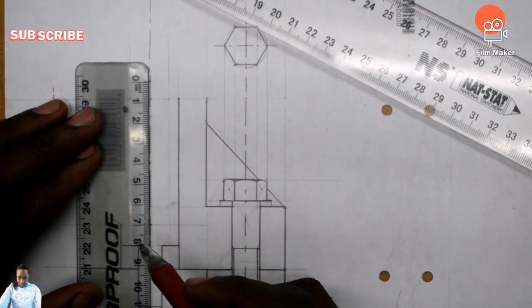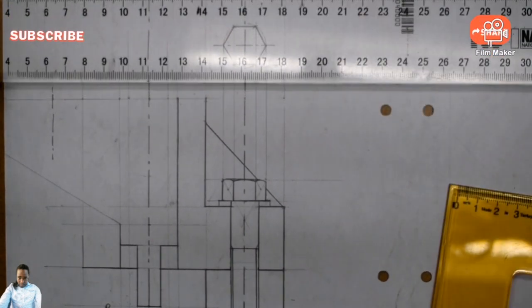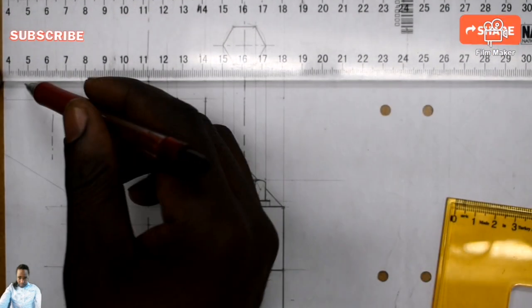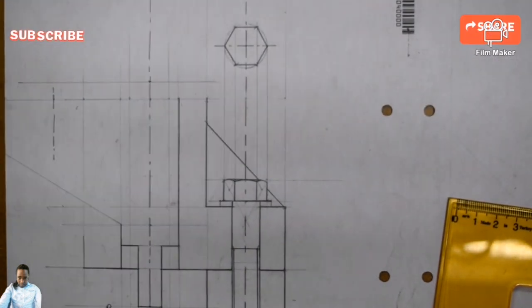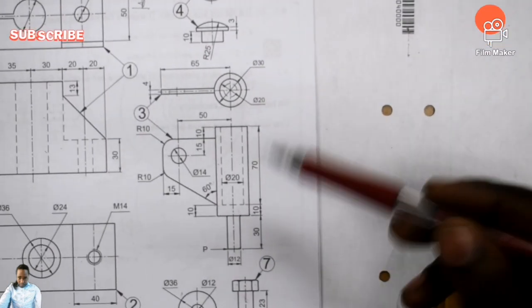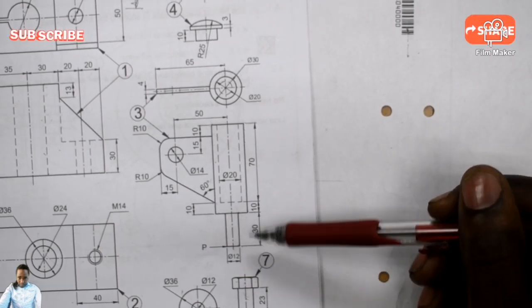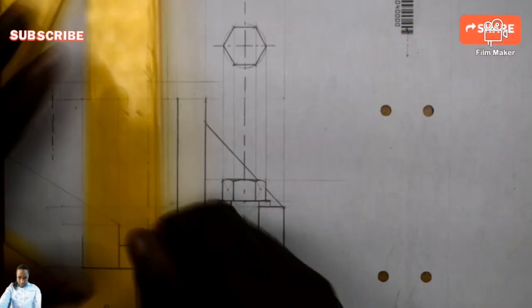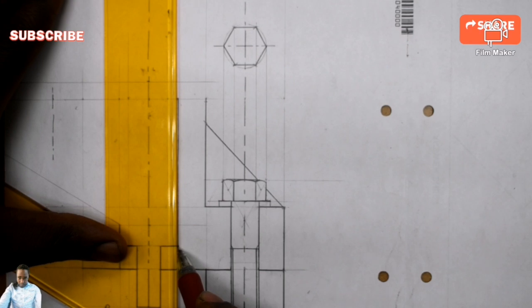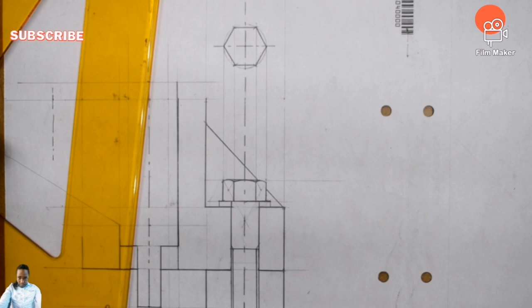And so it's right there, 70 millimeter. And then right here, where my 70 millimeter ends, I can put this horizontal faint line. That's where my 70 millimeter ends, isn't it? Then that's the true height of what? Complete height of my item 3. You understand? So which means I can project this line up until right here, up until right there.